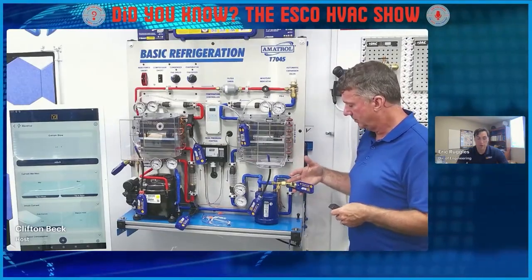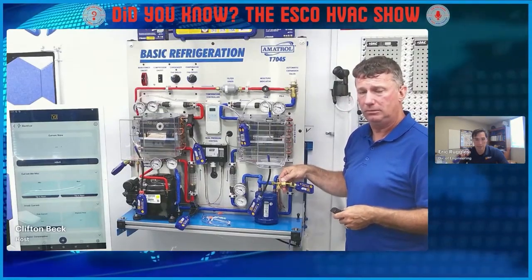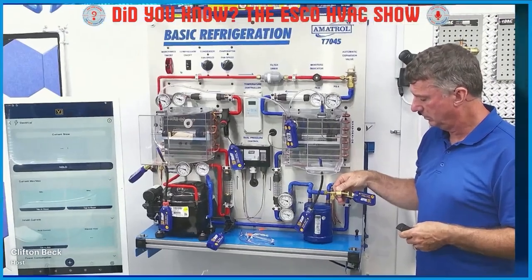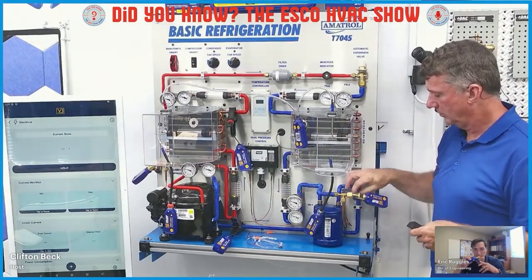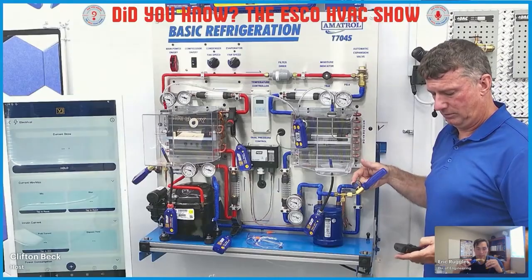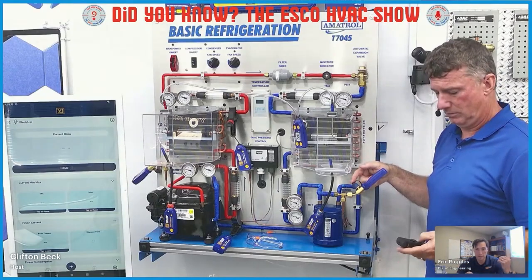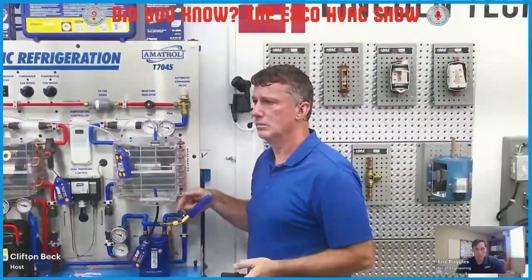So yeah, quarter inch fittings. You can get adapters for 5/16 if you need to. But they just screw on normal with the Schrader core depressor in them. They also have an auxiliary port on the bottom, so there's a T built into it, if you will, if you need to add a hose to actually charge or anything through the system. So it's nice to have it built in. But right there, all you've got to do is screw it on the Schrader core and then turn it on, which is the little yellow button on the blue screen.